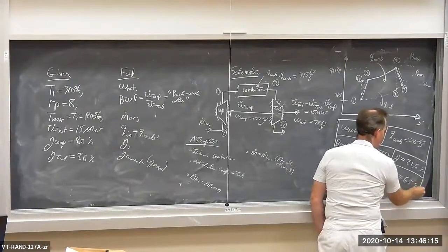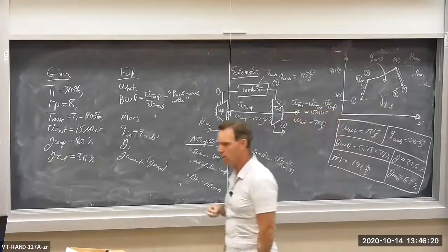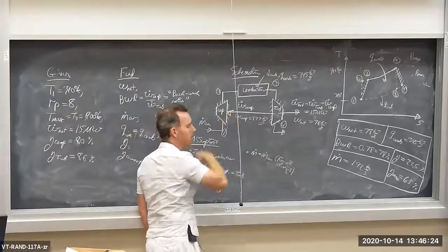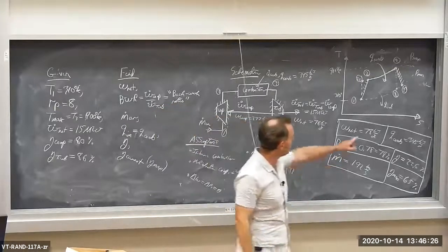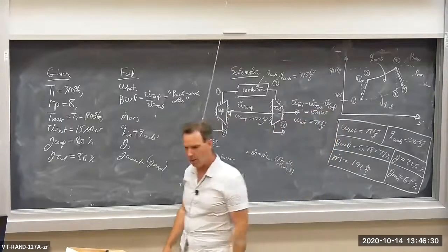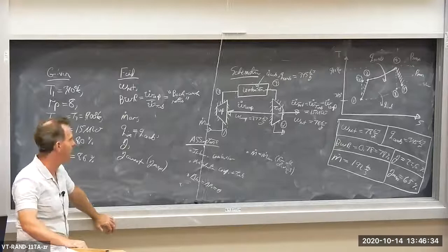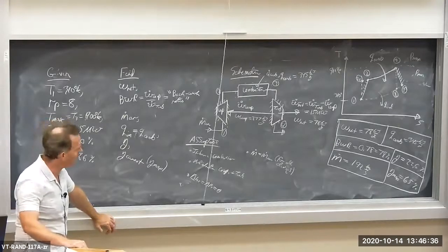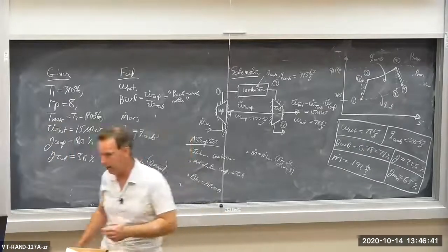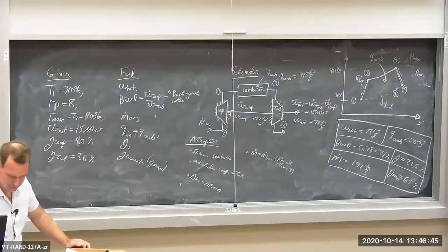Okay, it's due to the fact that the heat's being received at low temperature for much of the cycle, and we have all these inefficiencies going on in the turbine and compressor. It also has to do with the heat being rejected at temperatures other than the minimum temperature, and that results in heat transfer across a finite temperature difference outside the device. Okay, we've calculated everything in sight on this problem. I hope you have a good handle on it. Take care, ladies and gentlemen.